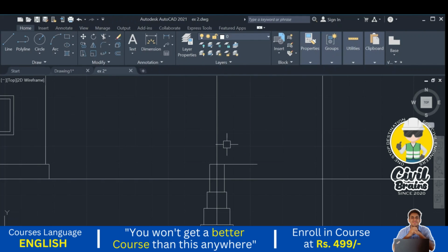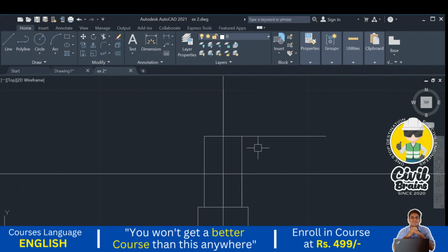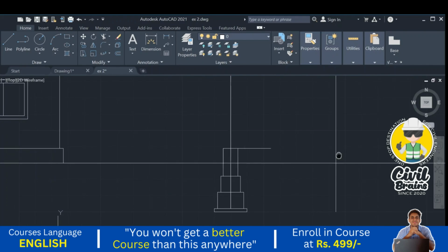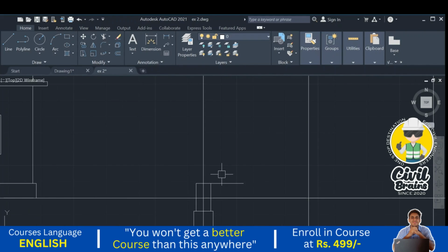So above the plinth, once we construct this, it is 0.45 at the plinth top, but we are providing the PCC over here also. We are also providing the PCC over flooring here, that I will show you later. Okay, above the plinth there is a superstructure. So what is the thickness of the superstructure or thickness of the wall? That is 0.23, correct? So we need to draw that one, 0.23, that is offset. Press enter. 0.115, and I will just trim the extra part.